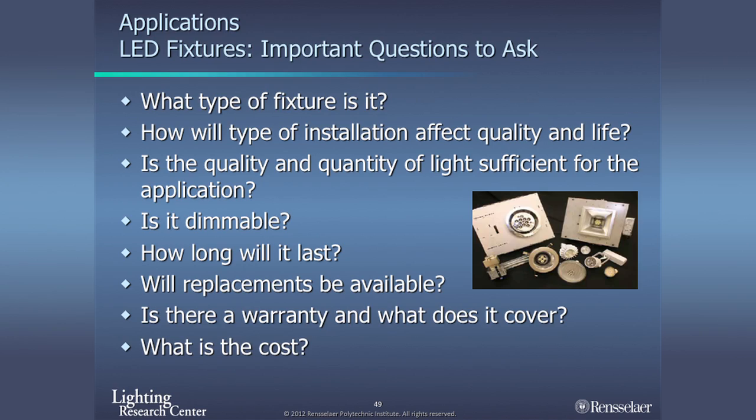These are electronic components. And what happens when you buy 1,000 electronic components that you put in your building? 6 or 7% of them are going to burn out in the first year. It's just the way things are made. There's just no way around it. They call it the bathtub curve, where a few things die at first and then it levels off and everything lasts for a long time, and then you get a lot of deaths at the end. It looks like a bathtub.